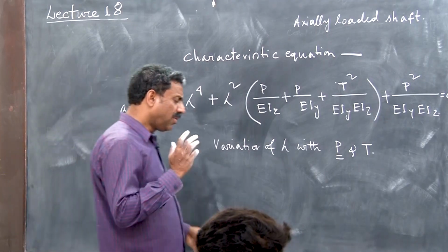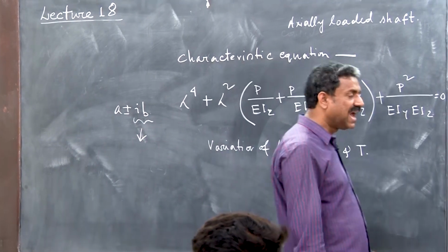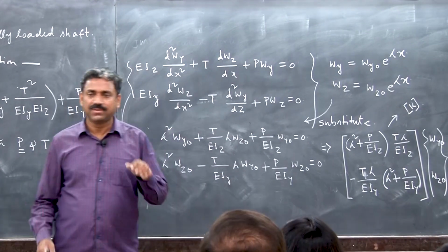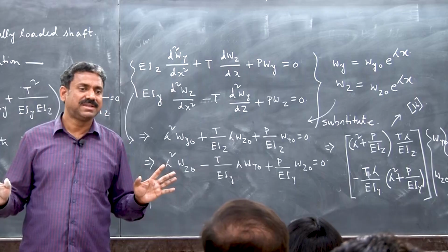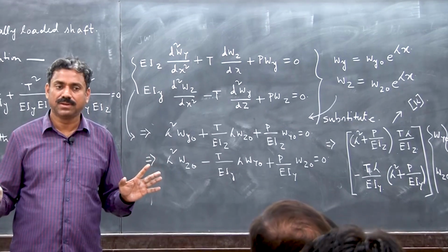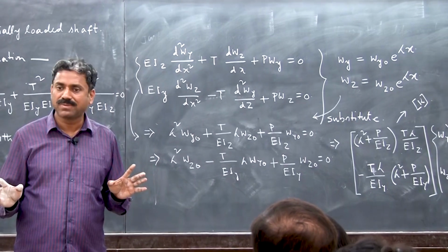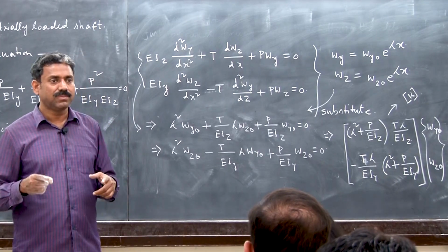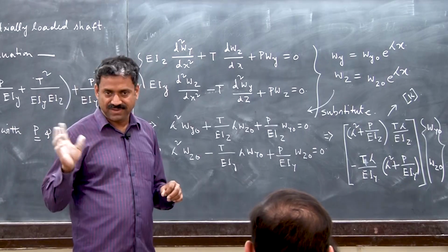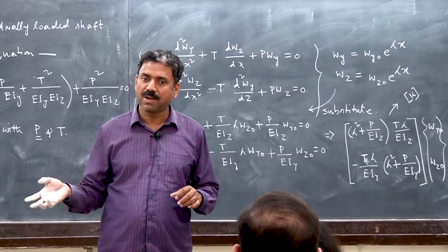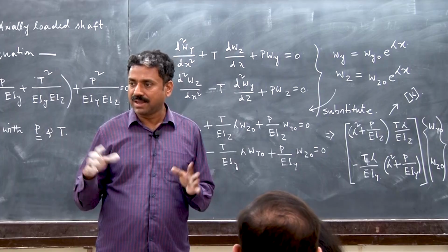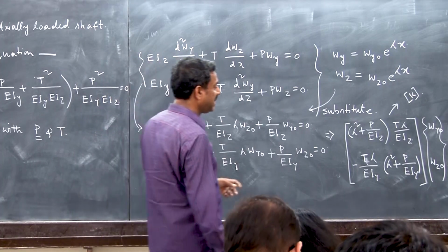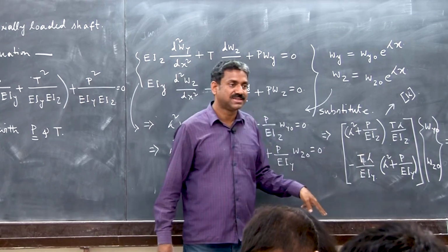But what I want to point out for this system at least is that here you see the case in which the load is not changing with the deformed configuration of the structure, yet the system is non-conservative. So non-conservative loading can be identified by physical consideration, whether it has the potential to pump up enough, unbounded energy, or secondly, a very good mathematical check is the asymmetry of the system matrix.